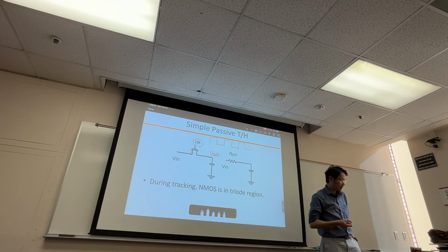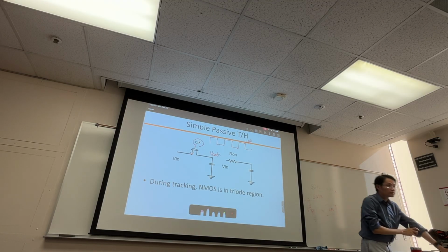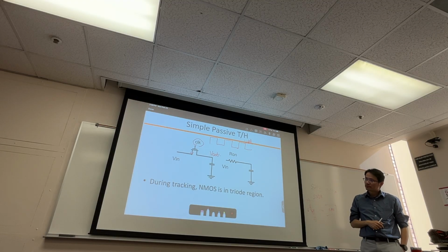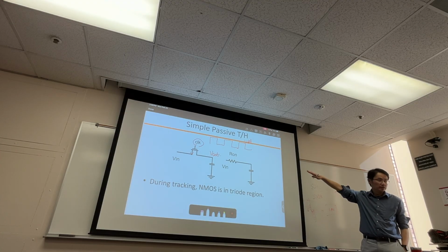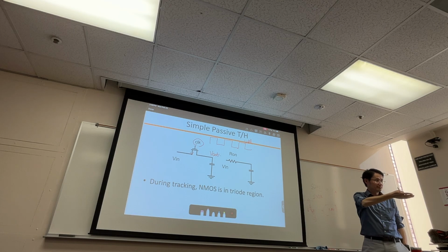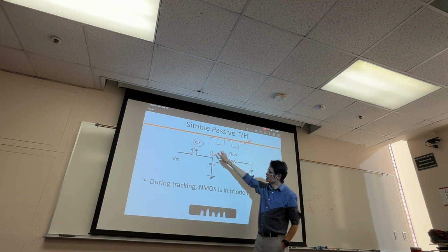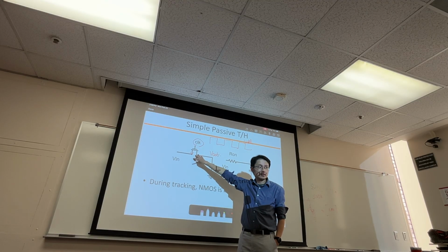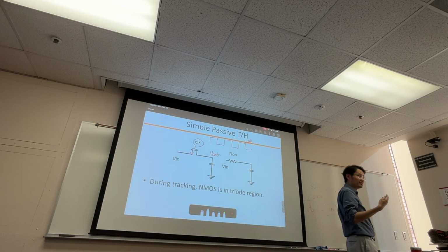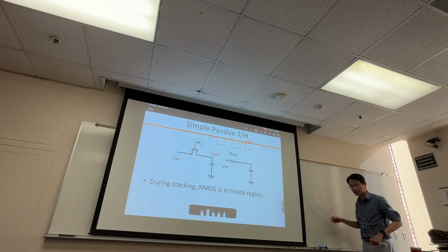When the gate of the NMOS is high, only linear, because it's supposed to act as a switch, so your VDS is small. So this will be in the linear region, or triode region, because it's really just on and off. In the triode region, this transistor looks like a resistor. Do you agree? What is the IV curve in the triode region?